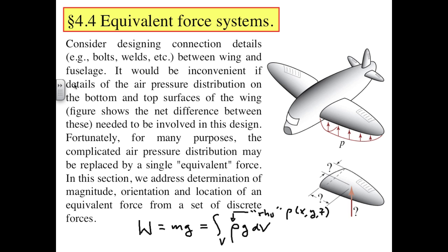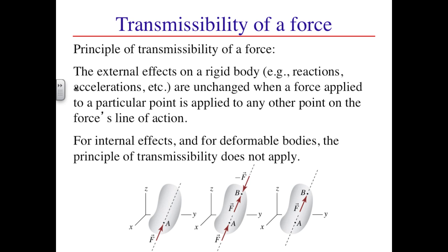We are permitted to slide a force along its line of action, but we are not permitted to displace it, that is, to pick it up and place it on a parallel line of action. We are not permitted to do the latter as it changes the nature of the rotation the force tends to impart to the body. In contrast, moments are free vectors. They have the same influence everywhere on the body, imparting a pure rotational load, and we can move them around at will without changing the nature of how they affect the body. We refer to this ability to slide the force along its line of action as the principle of transmissibility of a force.